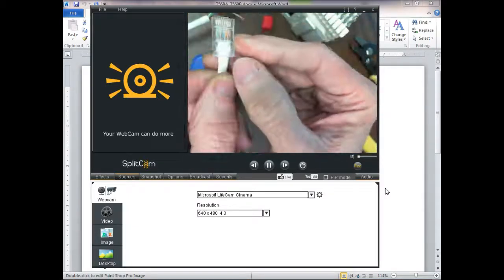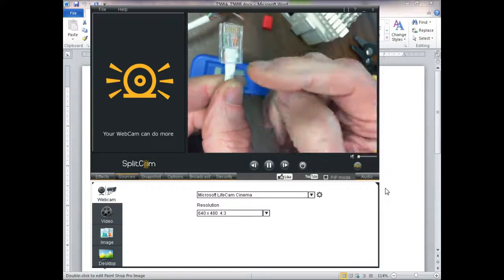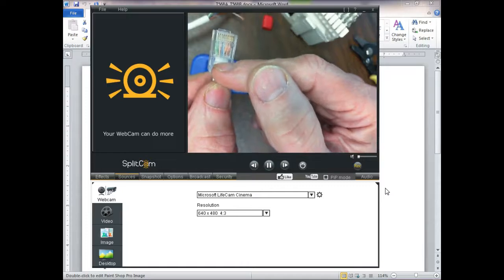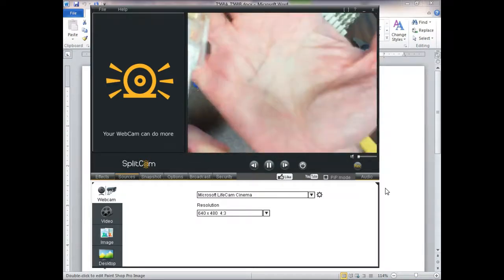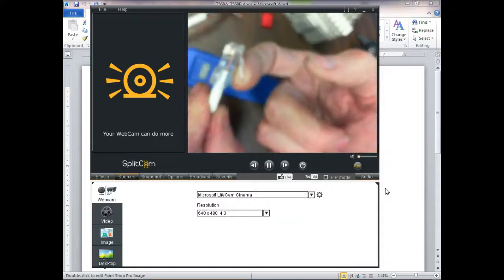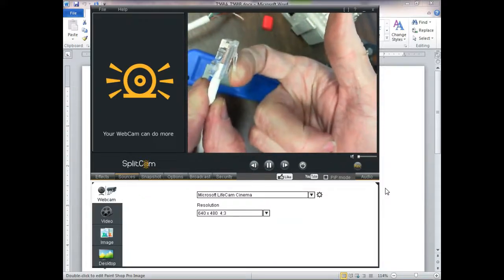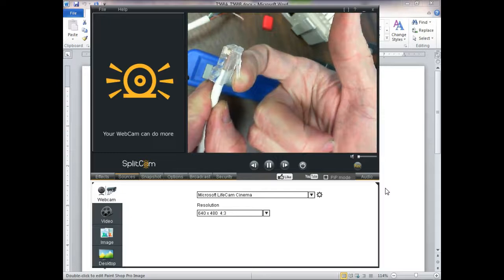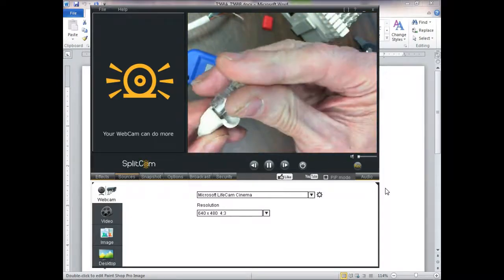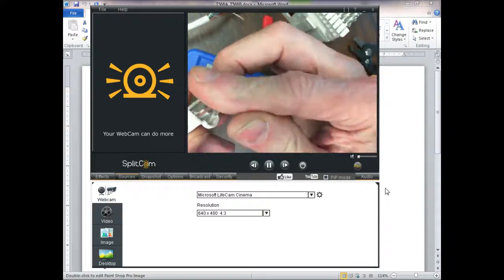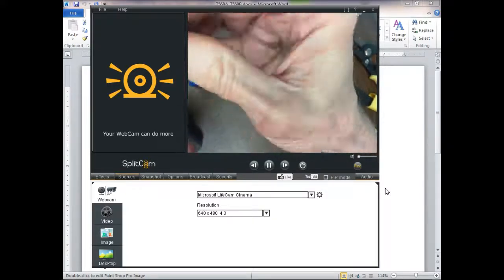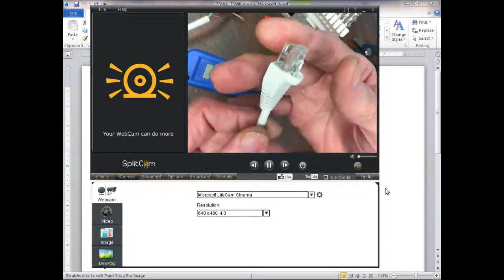And when you crimp it, it's got a crimp for the jacket. And this gives people problems too. They don't get the jacket under the what? The crimp. And now your conductors are handling all the stress. One of the biggest problems we have is this little old plastic tab being broke off. And what does this plastic tab do? It locks it into the female connector, right? You understand? So what we need is we have these little protectors that they come on, and what does it do? It protects that little latch.